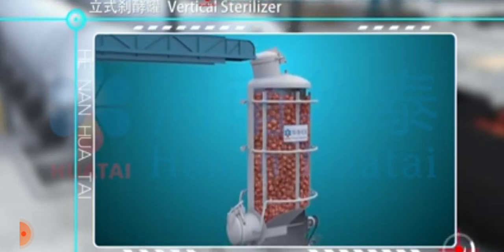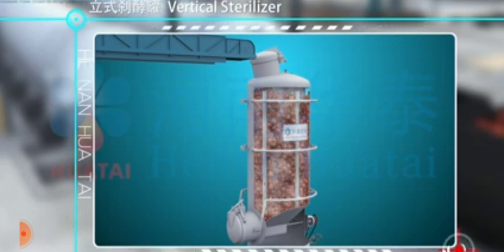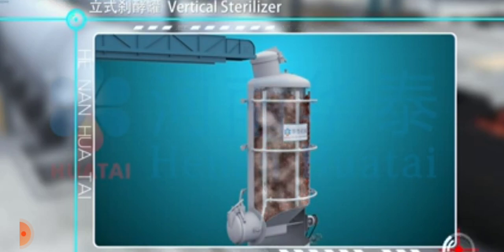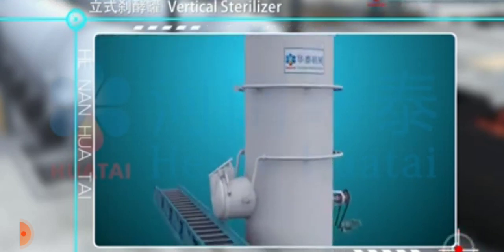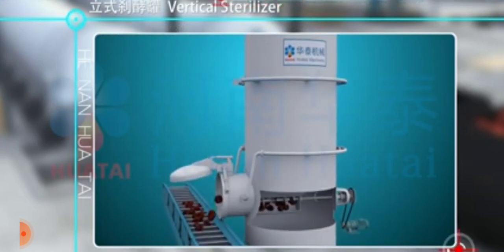Start filling with steam. Sterilize palm fruits under certain temperature and pressure. After reaching the preset sterilization time, empty the steam. Materials are discharged from the bottom screw conveyor.